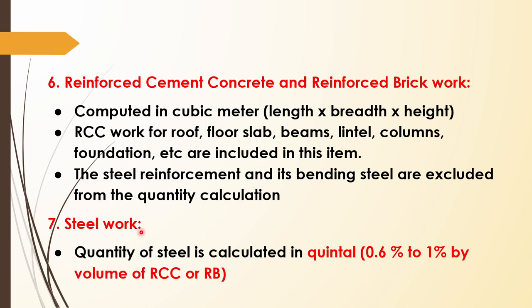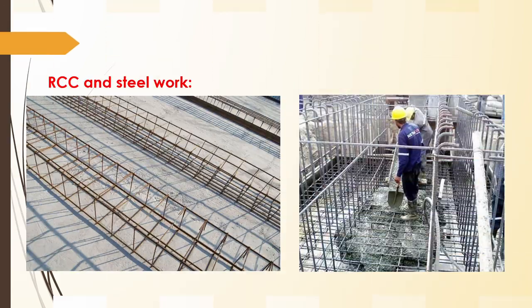Now steel work. Steel work means inside the reinforcement we will provide steel members, right? This quantity of steel is calculated in quintal. For example, we take 0.6 to 1 percent by volume of RCC. If we got 1 meter cube of RCC work here, then 0.6 to 1 percent of that 1 meter cube will be steel. That is how we will take the steel work. So this is about the RCC and steel work.